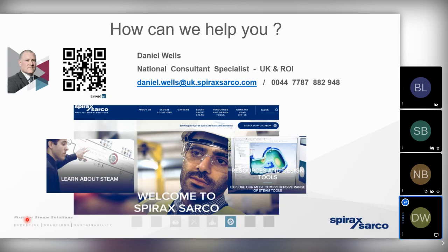Crikey, that is a good question. Typically, and I'm talking about a plant steam system here rather than a clean steam system, we want to vent the air at the occasional high point. So if the steam is going up a riser, that's where the air will naturally climb to. We want to vent the air away at that point.